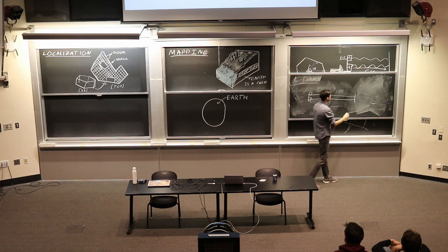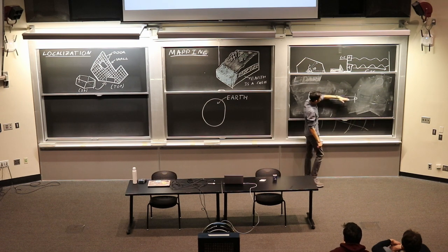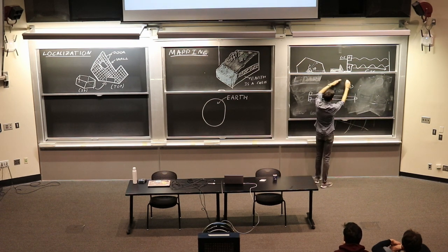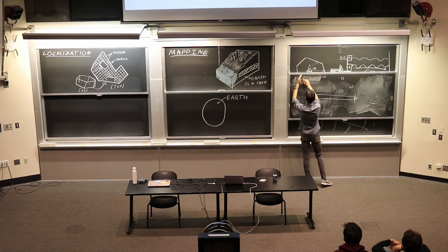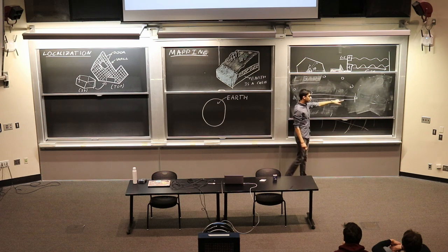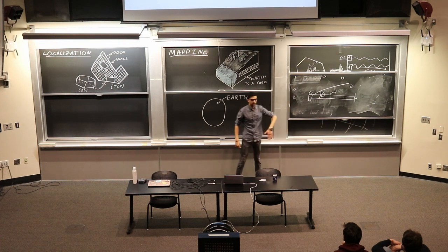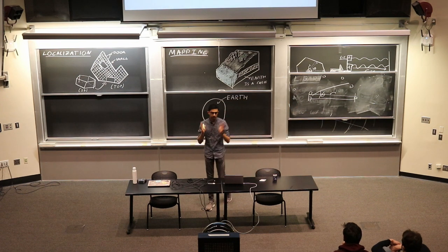And then it measures the distance to this specific point over here. But a LiDAR also spins around 360 degrees. So as the LiDAR spins, you're going to get a point here, a point here, a point here, and so on, and you're going to get the distance R, and then the angle theta at which it measured that distance. Theta equals 0 is the front of the LiDAR.